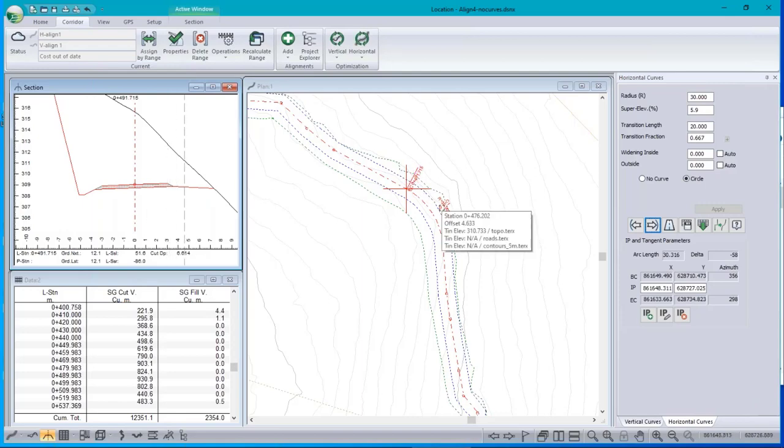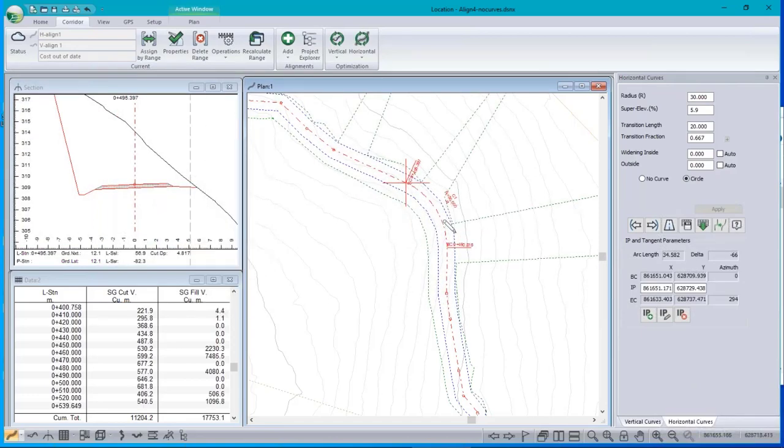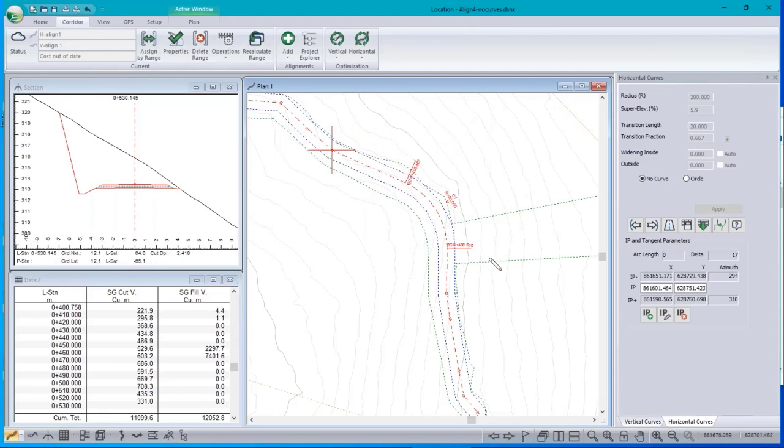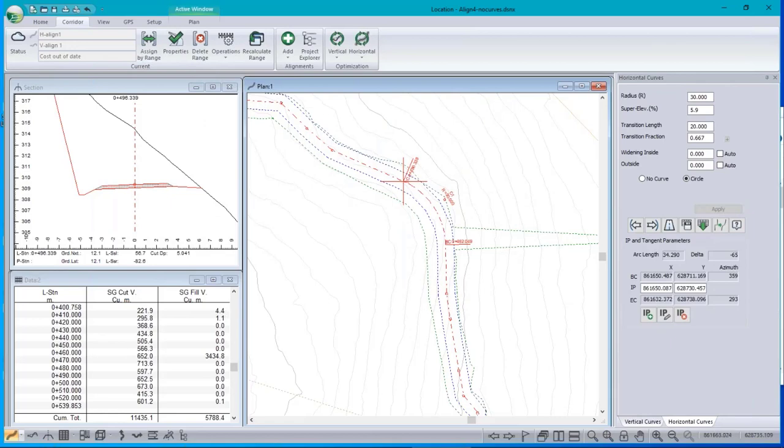So now all I can do is move this point here, because that's dependent on the curve. And you can see I've got a problem there and there. Here, well, I think I can move this back a little bit. That's not a problem. Oh, and now I've only got a problem here. So if I just move the curve that way, oh, too far. Okay, I'm back just a tiny bit more. Good. And now it looks like I've accommodated that curve with everything being full bench.